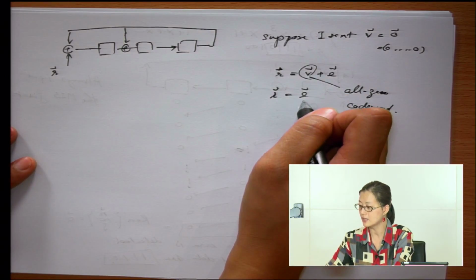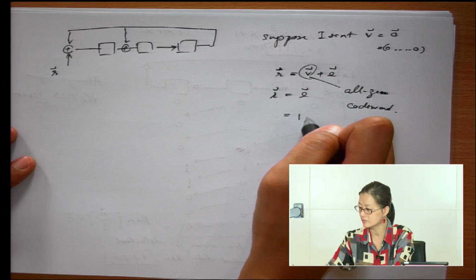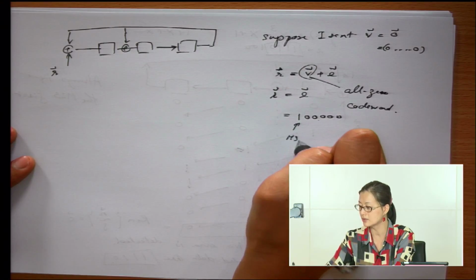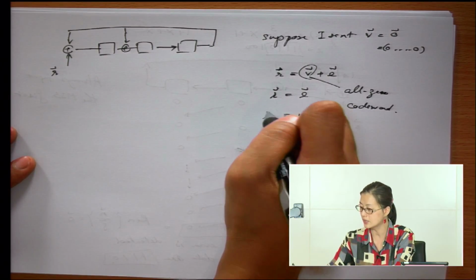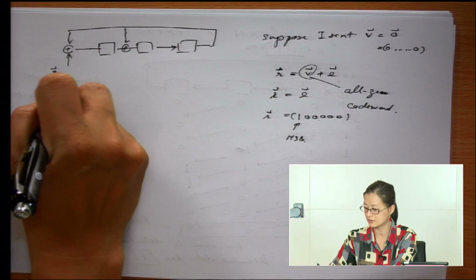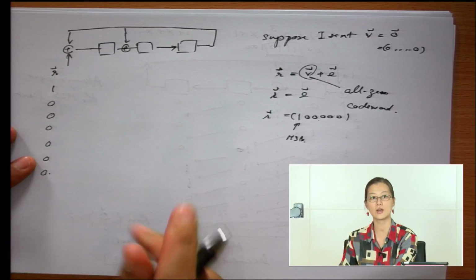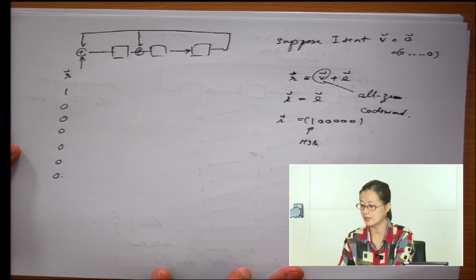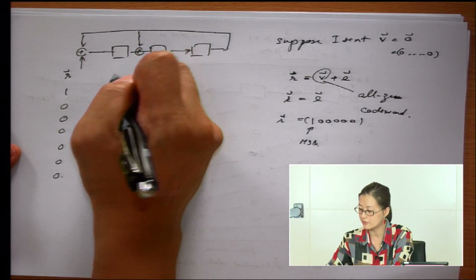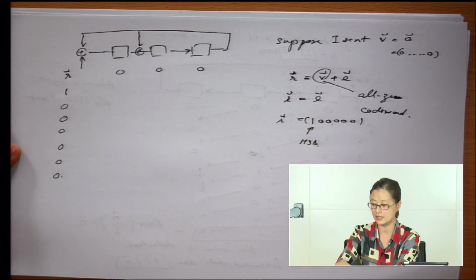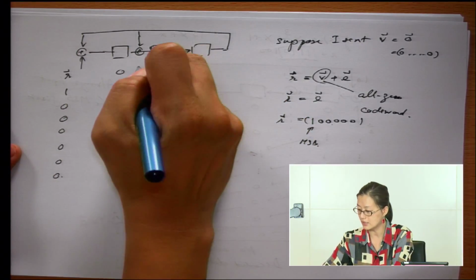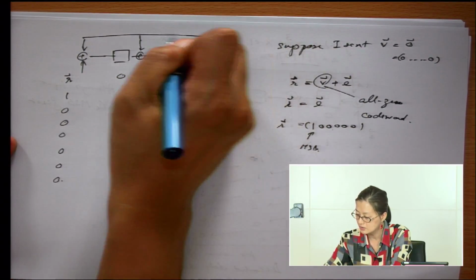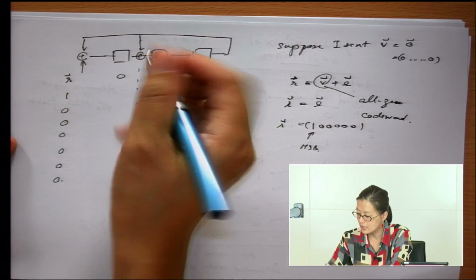So if I have the error in the first position, in the first most significant bit, I will have the received sequence look like this too. I put the first bit, the most significant bit, into the circuit. First I initialize 0, 0, 0, and then I have the boundary here. Now, when 1 comes in, what happened? This one is shifted over here.